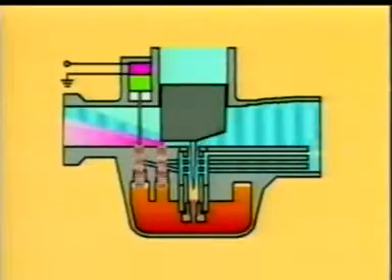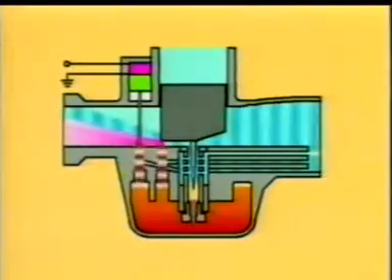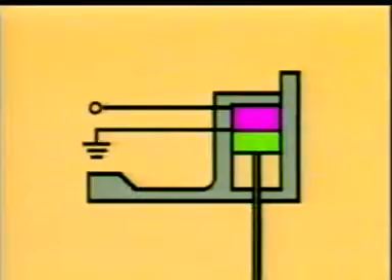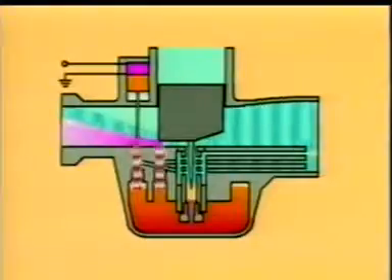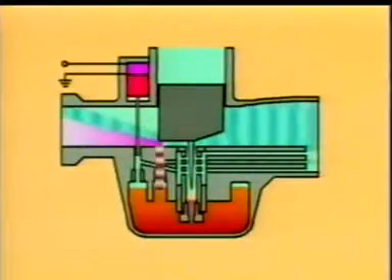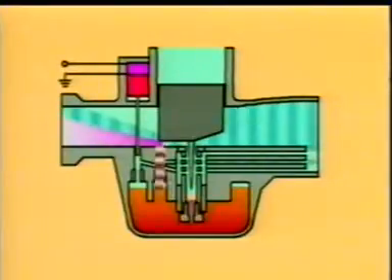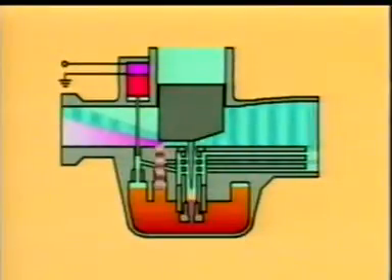When the engine is cold, the wax is also cold, so the starter valve is pulled upwards and a rich fuel-air mixture is sent to the engine. The engine is then started up and the current produced by the generator begins to flow to the heater, which gradually warms the wax so it begins to stretch. When this happens, the starter valve begins to shut off the passage little by little, decreasing the amount of fuel dispensed until finally, only the fuel-air mixture from the pilot system is being supplied to the engine.